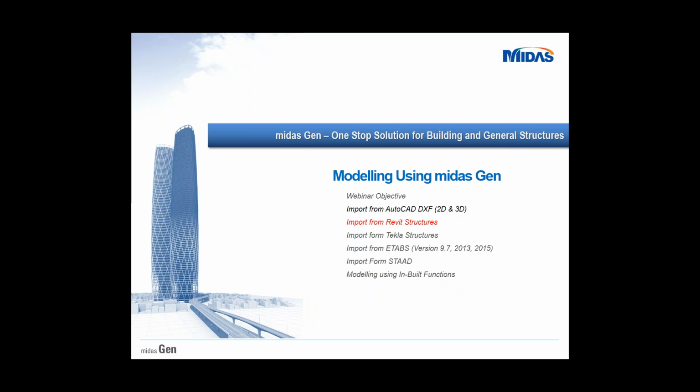And another question from Mr. Amar Dosari. What about the openings in slabs? Sir, for example, if in AutoCAD you're modeling the slab as a 3D face and you're providing an opening in that, the opening is also taken care of by the program. Automatically, it will import the opening as well, if it is modeled as a 3D face. But if it is modeled as a closed polyline, internally you need to create another boundary, which is not a polyline, which is 4 lines, which makes the boundaries of your opening.